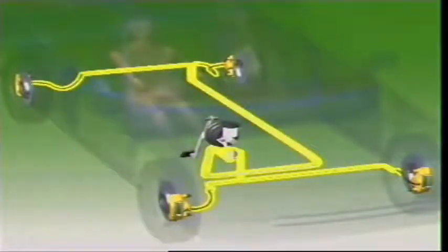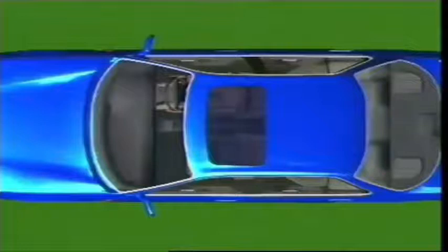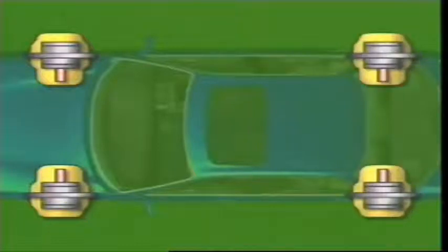On light vehicles, both of these systems are hydraulically operated. The brake pedal operates a master cylinder. Hydraulic lines and hoses connect the master cylinder to brake cylinders at the wheels. Most modern light vehicles have either disc brakes on the front wheels and drum brakes on the rear, or disc brakes on all four wheels.